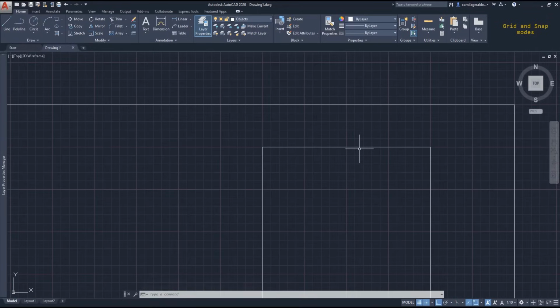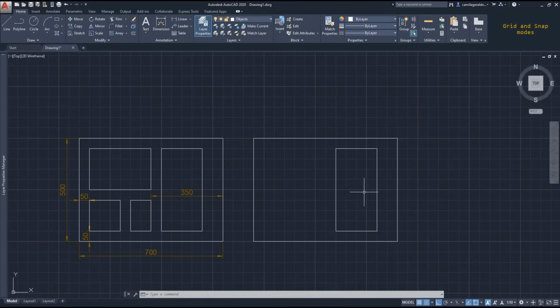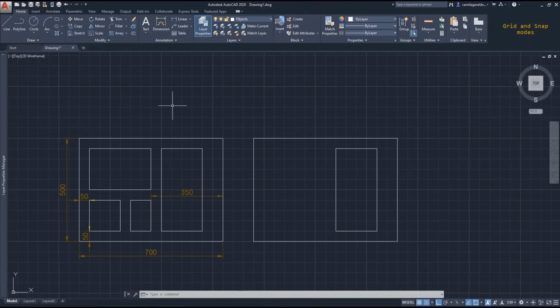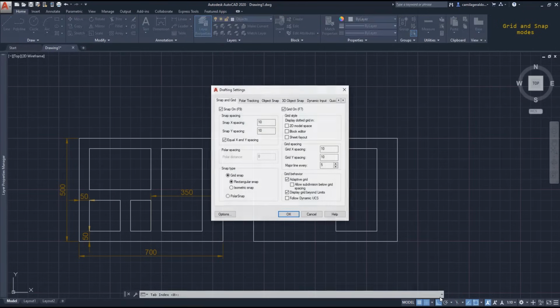You can zoom a bit to make sure that you click on the correct point, it's better. Okay, now let's learn to edit the snap and grid spacing. Click on Snap Settings to modify those values. It's in the first tab of the Drawing Settings window, here.